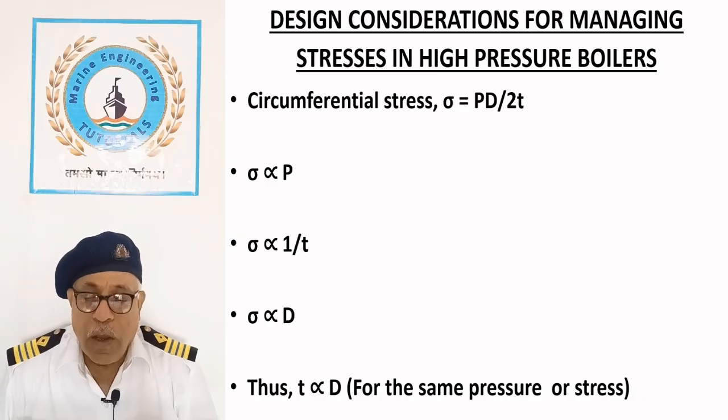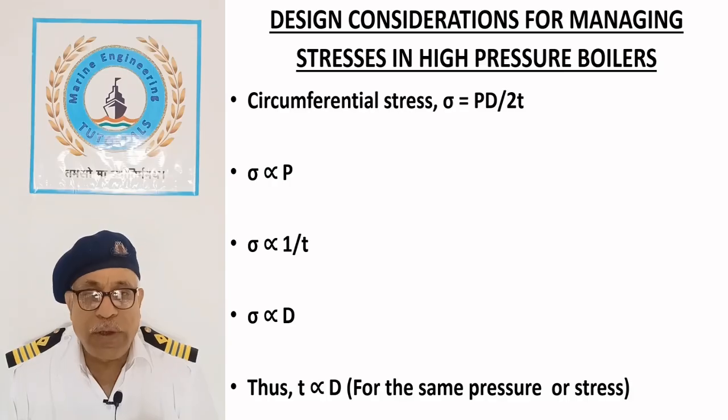simultaneously. A typical water to steam ratio of 5:1 to 10:1 is maintained during boiler operation. Therefore, the tube diameter should not be smaller than 40 millimeter, that is 1.5 inches, to avoid a low water to steam ratio, which could cause tube overheating and failure.